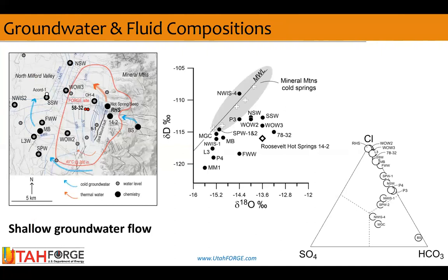First, I want to draw attention to water level data, which are used to map the piezometric surface in the water table. These are represented in blue lines, which are contours on the water table. In the vicinity of the Opal Mound Fault, this gradient is particularly sharp.